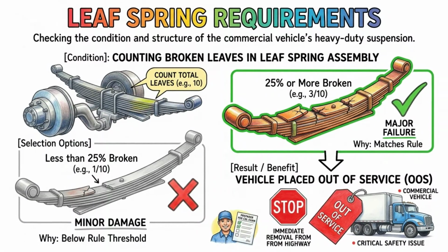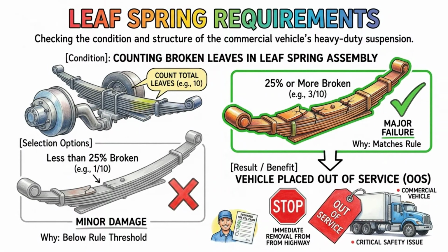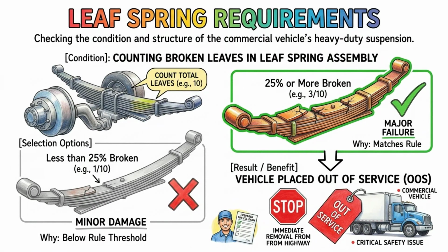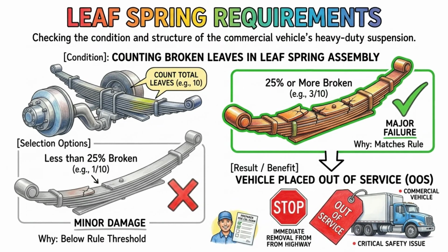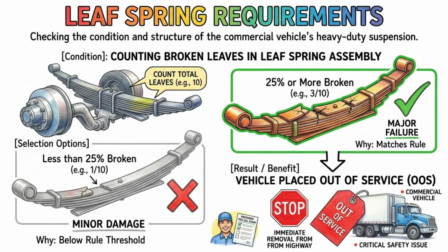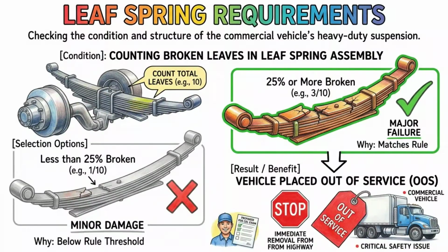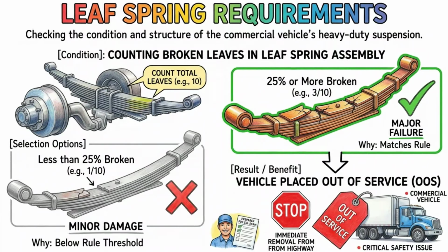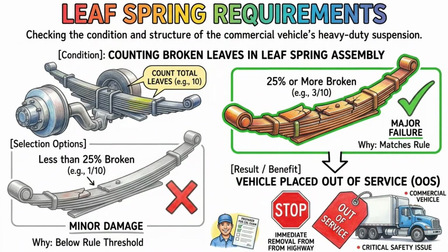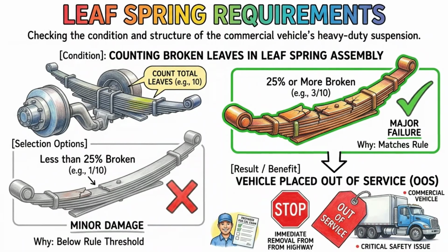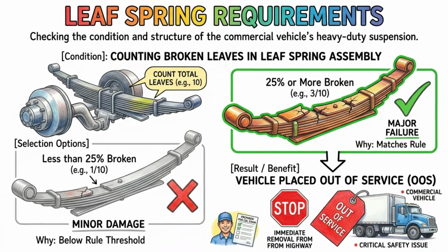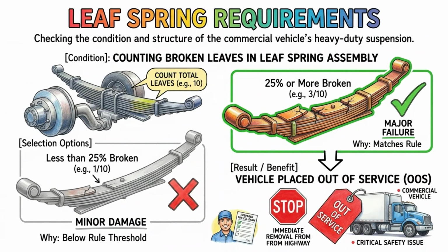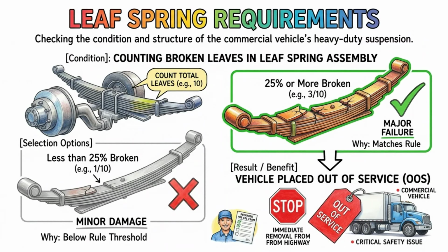Managing the space around your vehicle is critical because commercial trucks require significantly more room to maneuver and stop than cars. The general rule for following distance is to keep at least 1 second of space for every 10 feet of vehicle length at speeds below 40 miles per hour. For example, if you are driving a 60-foot rig, you need at least 6 seconds of following distance. If you are traveling faster than 40 miles per hour, you must add 1 additional second for safety. Space management questions are very common because rear-end collisions are a leading cause of commercial vehicle crashes.